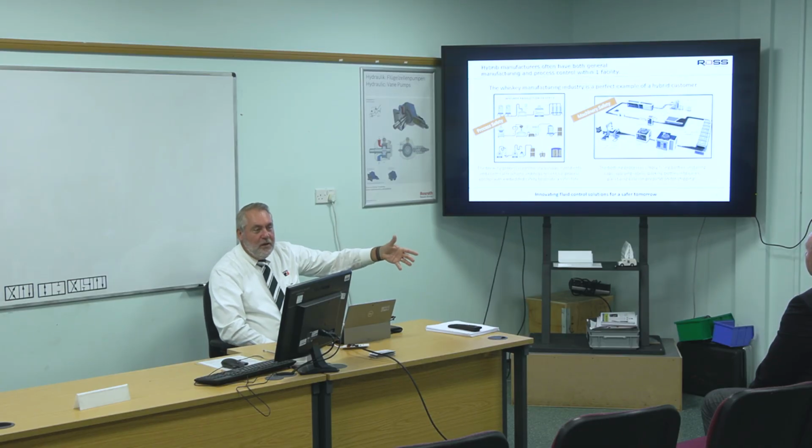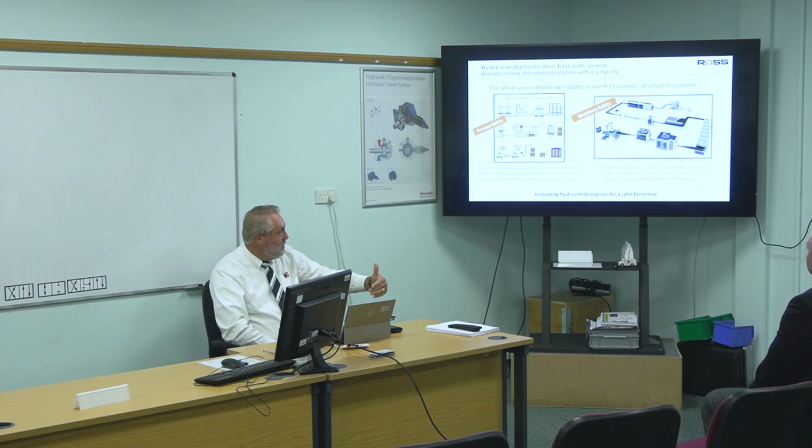And in this case, on the whiskey side, you have a depalletizer that basically unstacks the bottles and puts the bottles on a conveyor. It goes through a rinsing station that cleans them. That may even have some hybrid because you may have some cleaning fluids that go into those bottles, like isopropyl alcohol to clean the bottle. Then you've got an air blow that blows it off. Then it gets into the filler, the capper, the labeler. Sometimes there's pasteurization, so you're doing temperature control. And then you get into the labelers, inspection, case packers, and palletizers.